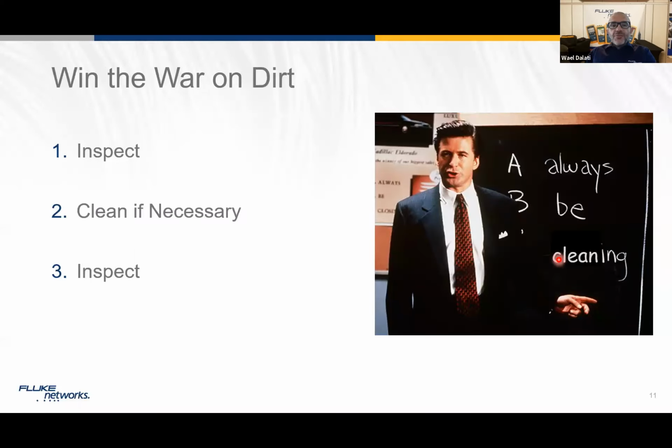So what we always recommend, the rule of thumb, the 3 rules for fiber: inspect before you do anything in fiber, inspect. Clean if necessary, then inspect again. Make sure if I am clean now, if my connectors are clean, that means I can move on. I can start connecting the tester to my cabling, or connecting the active equipment to my cabling system, because that would be my peace of mind.